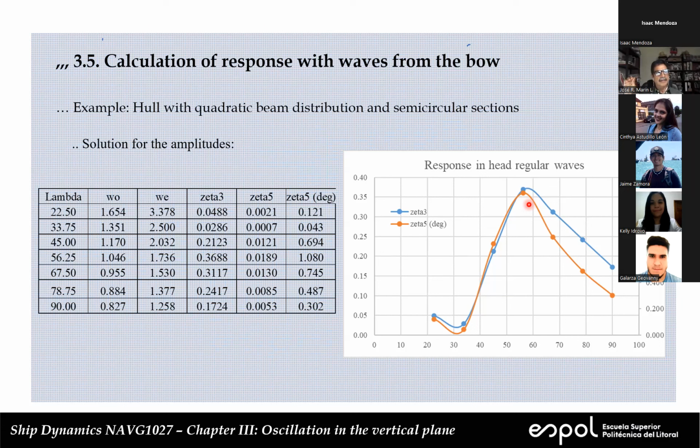And that's why, for example, when we do the tests, remember, we model from springs, we try to put an extra mass on the aft end, right? Why? Because in that case, the two natural frequencies, heave and pitch, tend to separate a little bit more.